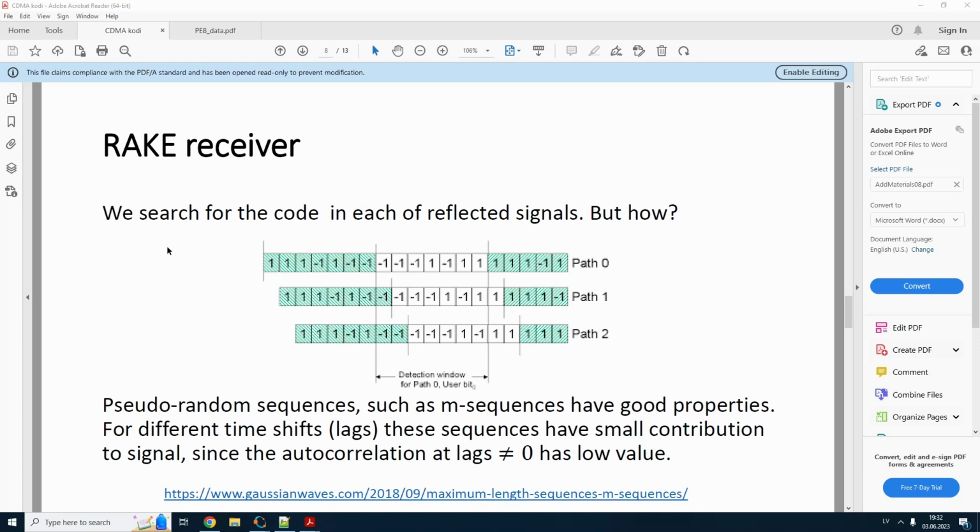So here we are not going to simply transmit data as we did before. Before, we simply generated some symbols and transmitted them as they are. Here we are going to use a spread spectrum approach to generate a specific code for each bit. So for example, this would have been +1, all of this code fragment, and this would have been -1. Just for example. Now instead of the symbol itself, this would be again +1.